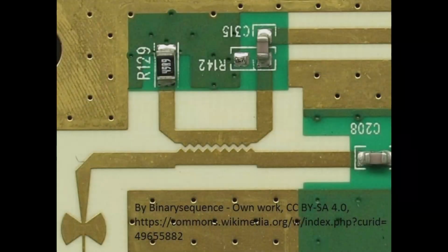Now, I said earlier that the even and odd mode phase velocities in a microstrip coupler are responsible for rather poor directivity, especially in weakly coupled lines. So what do we do about that? Well, here's one trick that is performed from time to time. Here's a coupler, and you can see that the edges of the two strips are sawtoothed.